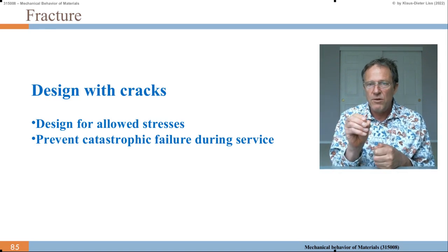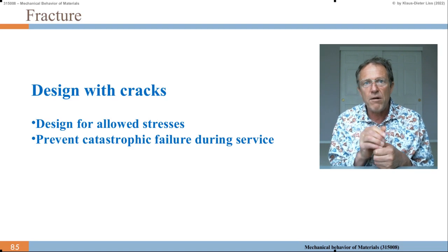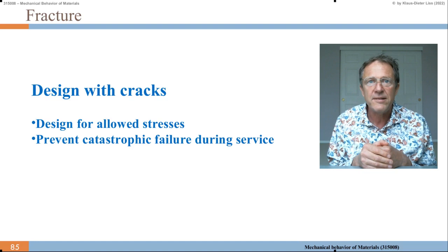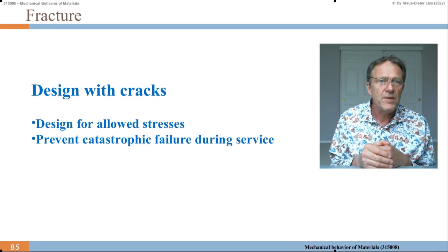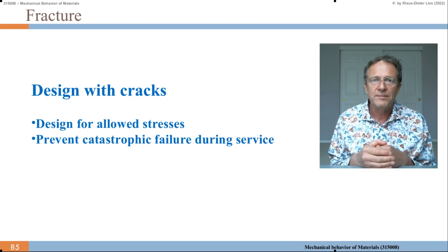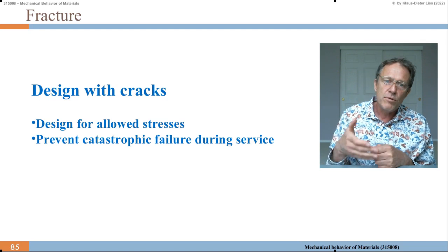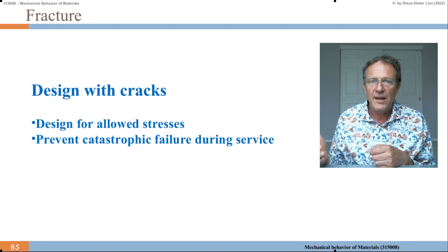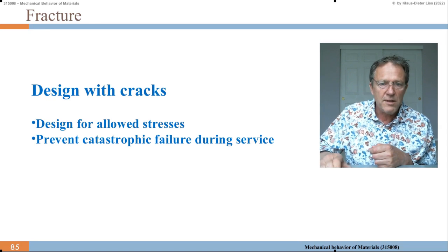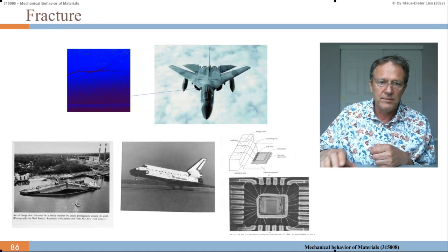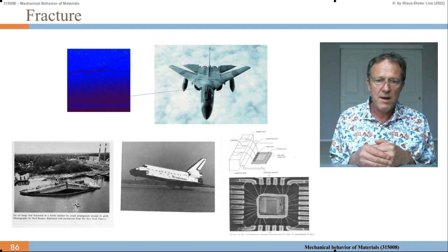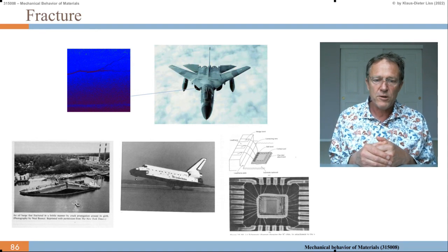Sometimes you check for cracks. If they are over a certain length, then you say you need to replace that part. You have to service the part. Otherwise, if it's under a certain length, which you can calculate with a margin, then you just continue flying and operating it. So, design with cracks, it's very important, of course, in the aerospace industries.